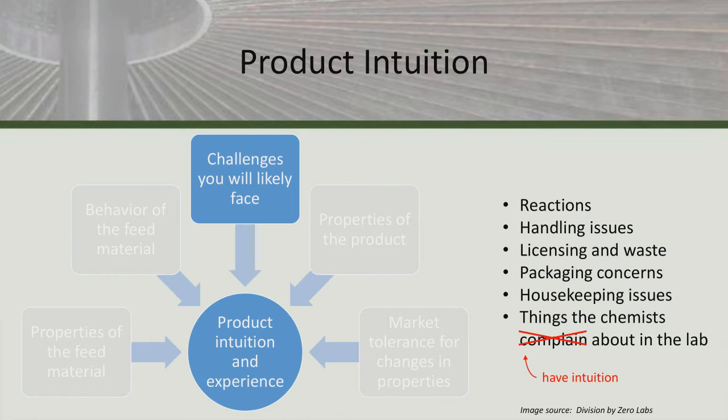Housekeeping issues, this mostly gets back to your quality programs. But most importantly, there's the things that the chemists notice in the lab. This is a special type of intuition that you really need to pay attention to. This is when they complain that, oh, the glassware is sticky. It's very hard to clean the glassware after I've handled this. Well, it's going to be very hard to clean the spray dryer too. There's a lot of valuable information that you can get by paying attention to those things.